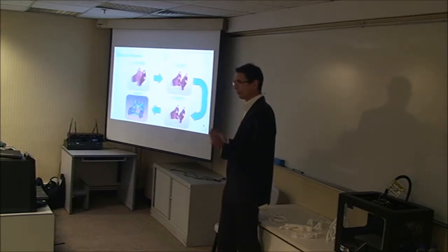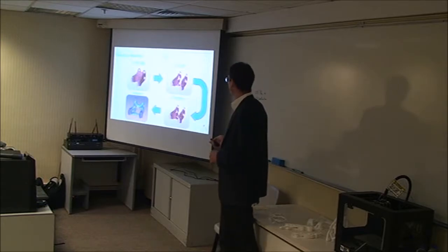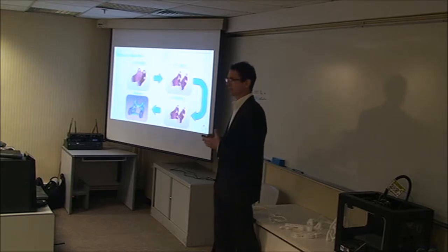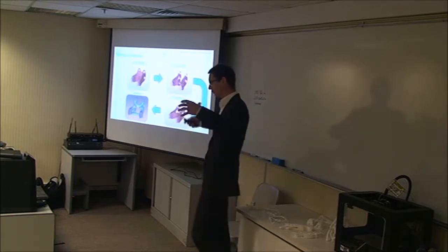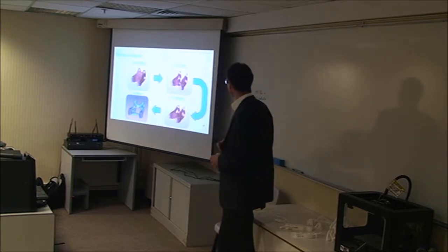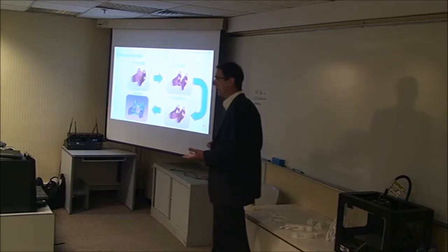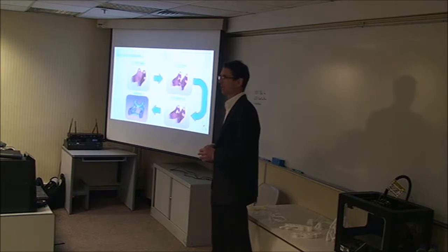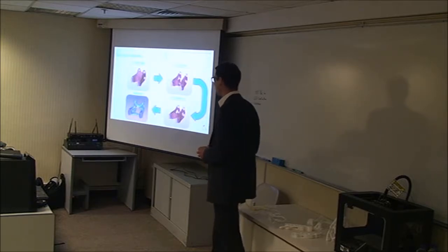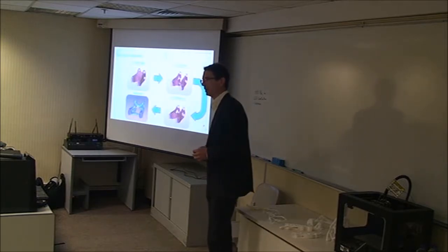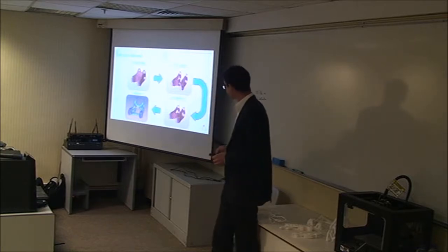Same workflow: design space definition. What space do you have? It's well related to the printer later on, how big that is. You optimize it, you interpret it, you derive the geometry out of it, and then you check whether it really withstands all the loads, and you have to compare against the material properties.